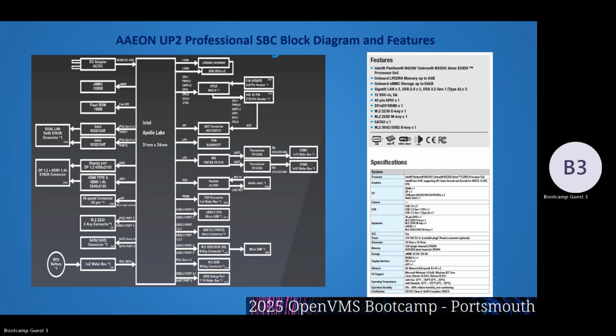So what can you get on the Aon single board computer? Well, this is what you have. You have USB 2.0 and 3.0 chips. You've got expansion capabilities. M.2 are called small form factor PCIe devices. You have a SATA 3 controller. You can go up to, I think, 8 gigabytes of memory, dual channel, a HDMI connector, 2 Intel Ethernet controllers, and we won't talk about the incomplete operating support list that's there.